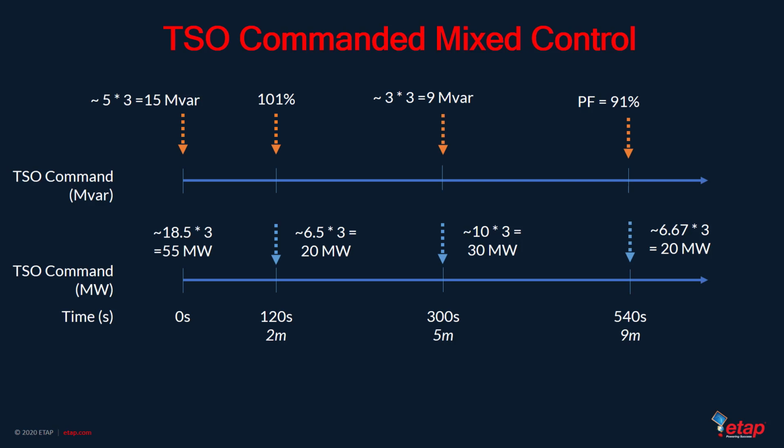And this, of course, must be simulated in practice as well. A meter at the point of interconnection basically tracks the plant's contribution as it's seen on the grid. Of course, if there's more irradiance potential than needed to maintain the set point, the inverters must be commanded to limit themselves. Purposeful limitation of the production, once again, is what we refer to as curtailment.